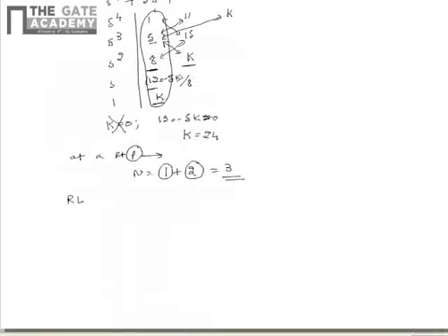And also we know that the root locus starts from open loop poles and ends at the open loop zeros or infinity. From this we can say that root locus starts at 0, minus 3, and minus 1 plus or minus 2j, and ends at infinity, as there are no open loop zeros.